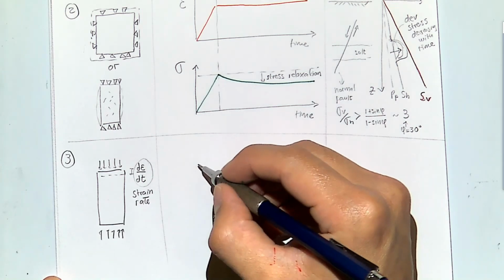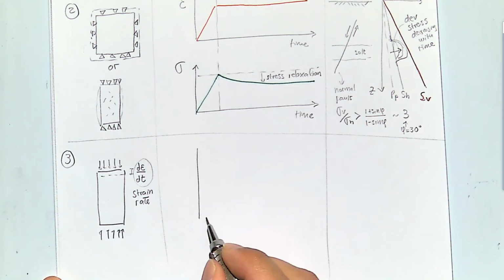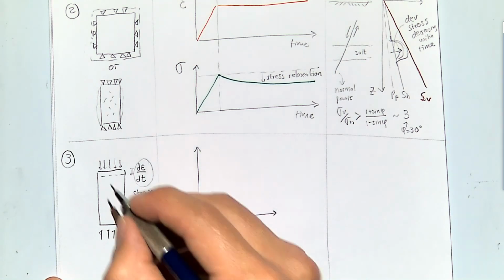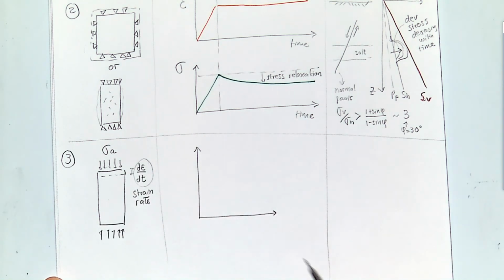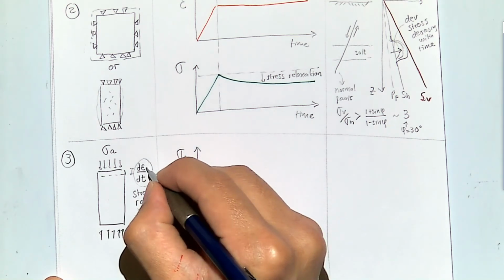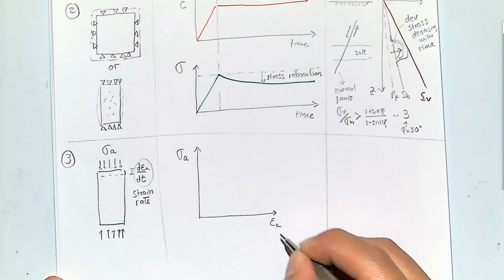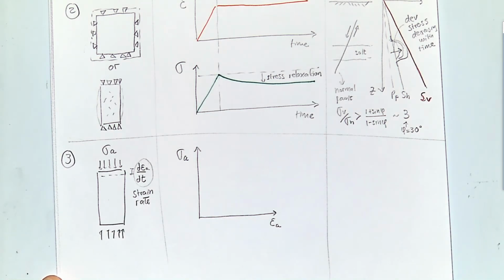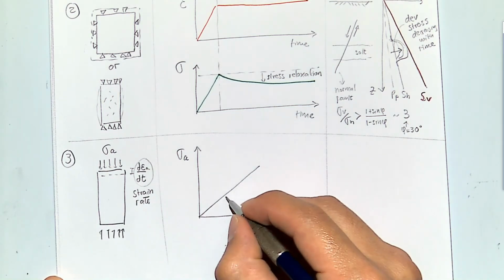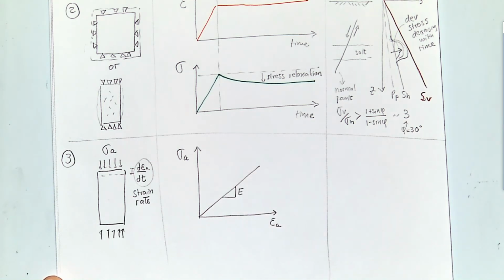All right, so for this particular example, if you were to measure, for example, the Young modulus, which is the change of axial stress divided by the change in axial strain, keeping the other stresses or the confinement constant, then you will find that if you do one test at a given velocity, this one is going to be E, and what do you think is going to happen?